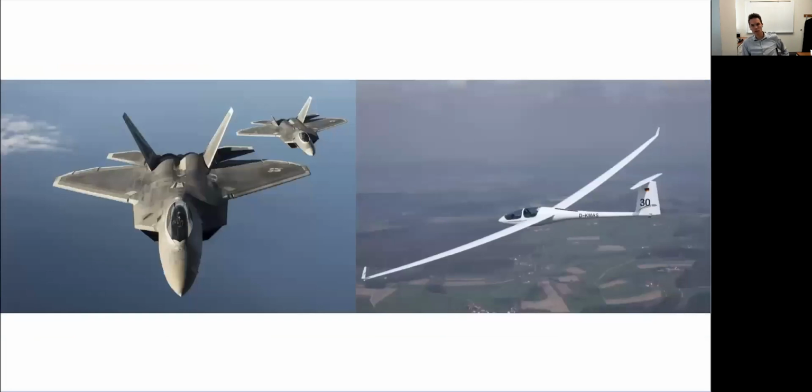We, of course, see this reflected in aircraft designs too. Large wingspan on the right, very efficient, can glide very far, or with powered flight get very far range, but not very maneuverable. They can't pull in their wings, so they're going to take longer times to turn, so there are pros of stability, but not very maneuverable. Whereas a fighter has a very short wingspan, but is very quick, able to maneuver and change. So depending on your requirements, you have to make some trade-offs. Again, you're going to pay for that in terms of induced drag.